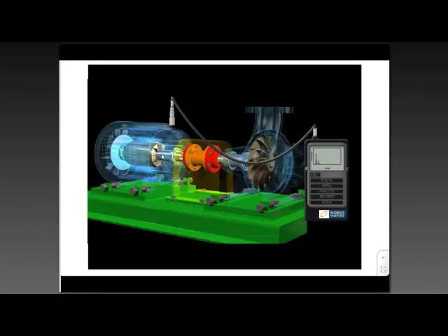So a sensor up on top of that bearing is not only going to pick up the vibration from that bearing, but from the other components. All the vibration sort of travels along the shaft through the bearing, the housing, and so on, up to the sensor. But the sensor there is sensitive to the vertical motion.